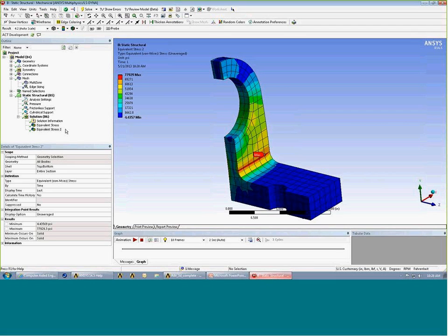So this obviously is a stress that is not converged based on our mesh. We have a difference of about 6 KSI between the average and unaveraged values out of, say, 77 or 80, so maybe 5 to 10% off.